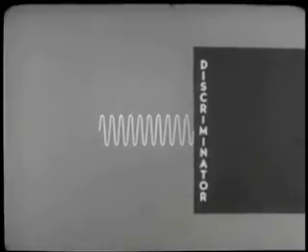Feed the frequency-modulated carrier into the discriminator, and its output will be an audio frequency voltage. Feed it an RF signal with constant frequency, and there will be no output signal. All FM discriminators do the same job, but not all do it the same way. For a briefing in the fundamentals of the discriminator, let's take a simplified look at how this typical discriminator does its job. We are primarily concerned with two things, the wave and the discriminator.